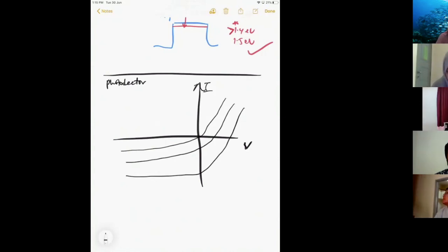In the PN junction. Most of the absorption or generation will occur in the depletion region, because whenever you have a PN junction, of course you have a depletion region, right? When you reverse bias it, you have a bigger depletion region, and all the absorption will happen there. So even a normal PN junction works. But if you make it PIN, it becomes better.